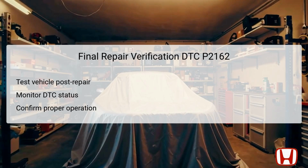After completing repairs, a final verification step is critical to ensure the issue has been resolved. Test the vehicle again, replicating driving conditions similar to those when the DTC was triggered. Monitor the Honda Diagnostic System, HDS, for any reappearance of DTC P2162 or any other related trouble codes. It's important to confirm that the transmission responds appropriately, the speedometer displays the correct readings, and there are no issues with shifting. By thoroughly checking each aspect of vehicle performance, technicians can ensure that the repairs made were effective and that the vehicle is roadworthy again.